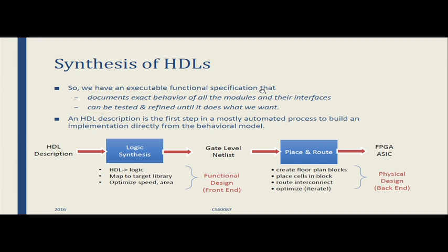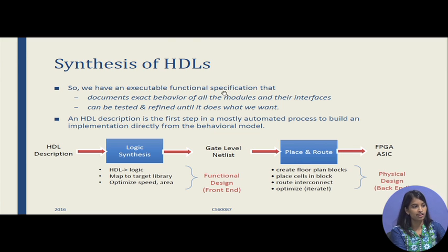So the executable functional specification documents the behavior of modules and interfaces, and it can be tested and refined. So that is what an executable functional specification is. So HDL is the first step to automate all the process of digital design. So this executable functional specification, we can take it as an HDL description, which is given to a logic synthesis tool, and we get a gate level netlist.